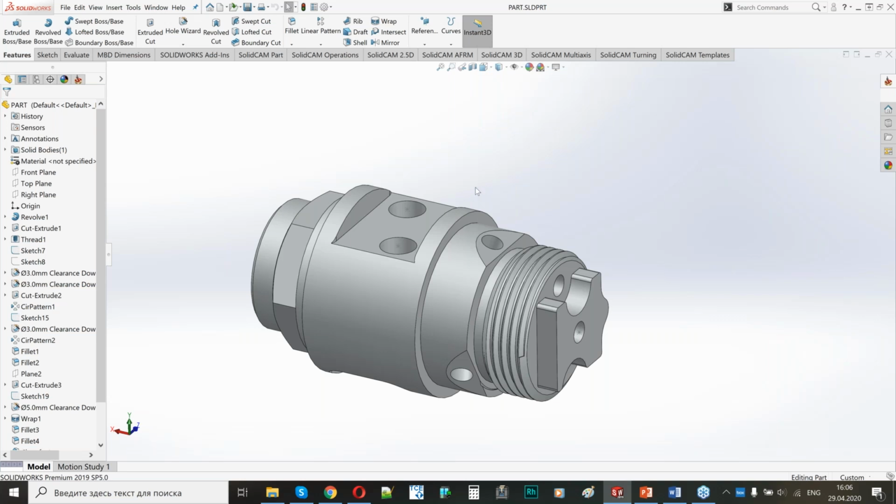As you know, on Swiss type machines, Z1 axis is performed with part movement in guide bush device, and cutting process should be planned with consideration of allowed Z retract distance. There is a limitation of allowed part length retraction because of Swiss type machine construction. This length depends on guide bush collet.